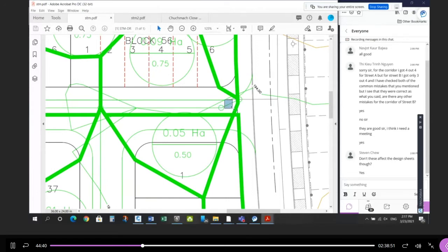And then this has just got nothing tributary to it. Everything, all of this is flowing through here. And the purpose of this little pipe is just to change direction. There's no additional area or flow coming into it. We still need to design it. And basically what will happen is whatever size and slope of this one, this will be exactly the same, because there's nothing more going into it. It's all the previous stuff. So we're just pouring into the top end and assuming it goes through.